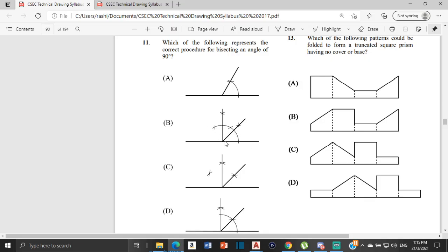All right, and to construct the 90-degree angle, we'd have to construct this right here with the 60 and the 120, and then bisect those and get the 90, and then bisect the 90 to get the 45. All right, so the answer right here would be B. Good. It could not be C because we don't have a point down here to use, or a point up here to use to bisect to get the 45-degree angle.